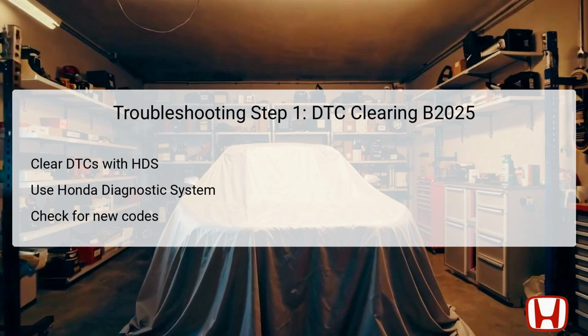This action allows the vehicle systems to reset and provides an opportunity to check for any reappearing error codes. If DTC B2025 is indicated again, further investigation is warranted. This initial step creates a clean slate for accurate diagnosis.